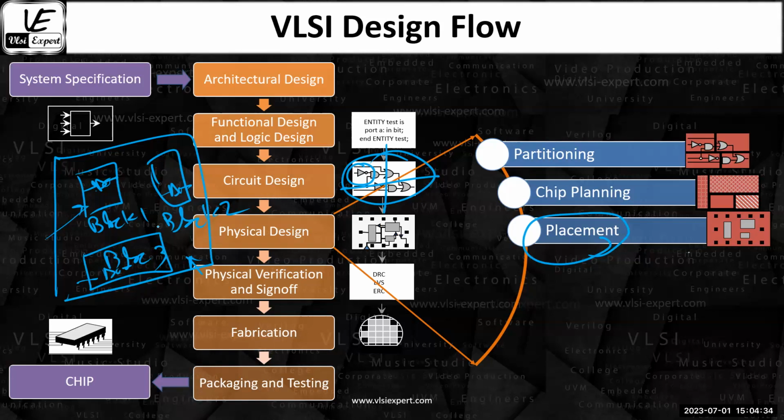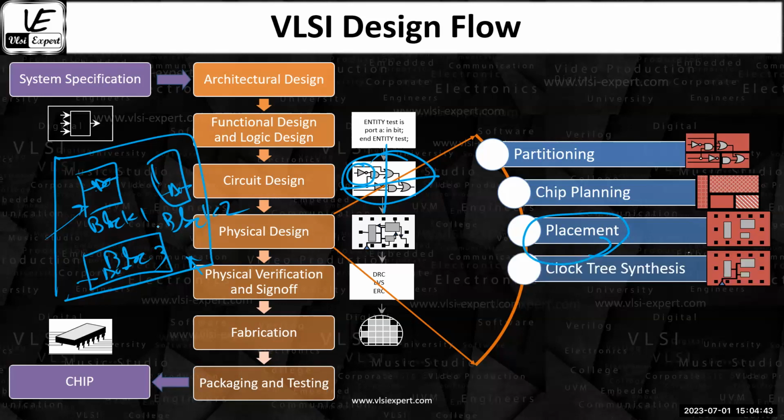Now block placement is basically part of chip planning or floor planning. So chip planning and floor planning are interchangeable words. Okay, then placement comes into the picture. Now once the placement is done, then the next step is clock tree synthesis.